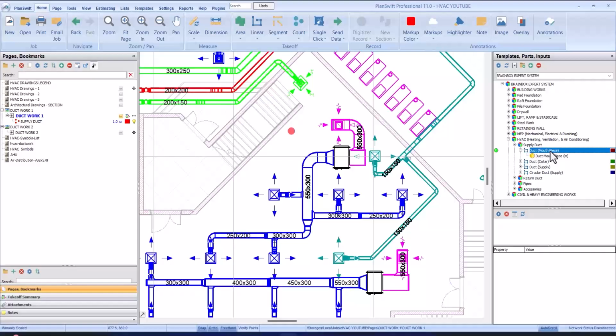The essence of getting your quantity in square meters is, let's say you want to fabricate your duct on site. You need to know the number of sheets to be used for your fabrication. So when you have it in square meters, you'll be able to get the sheet size and then divide by it to get the actual number of sheets needed. Then in your bill of quantity, you can measure it in meters.